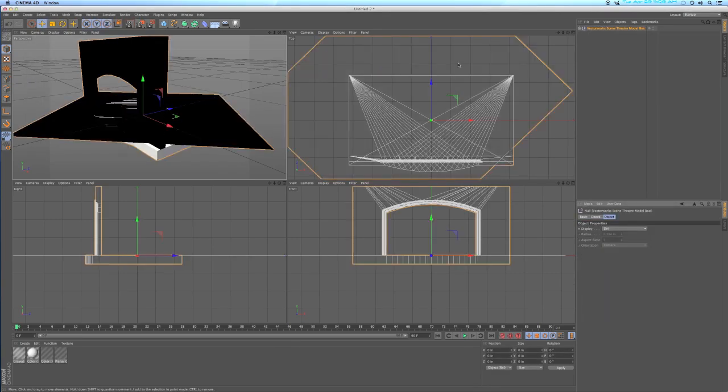And so here's our theater model box. Up here in the objects manager, it has this heading. That is like the whole grouping of all of our elements. If I click on the little plus symbol, it'll twirl it down. Now you can see that we have geometry, lights, planar objects, and cameras. It's under geometry that our actual model exists. So I click that to twirl it down, and it says design layer, and I click on that plus symbol, and now we actually see our actual geometry.